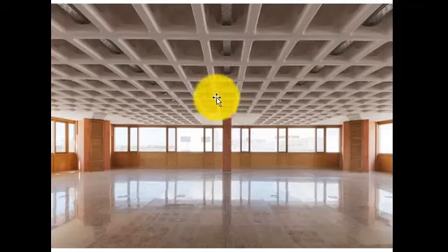So why should you consider using a waffle slab in any kind of design or any kind of construction you are involved in? You should consider a waffle slab in a case where a wide or large space or a long span is required without column obstructions. Remember, when you have a column that is not embedded in the wall, it is an obstruction.